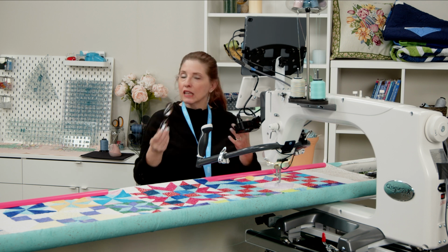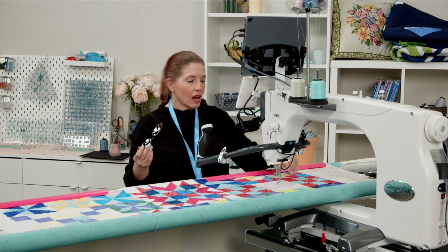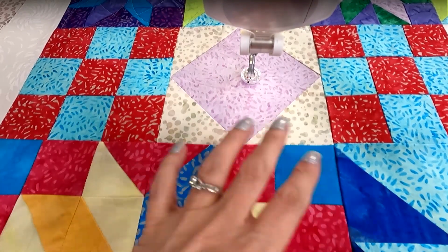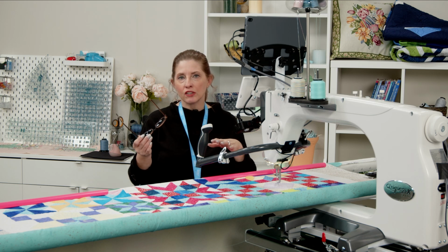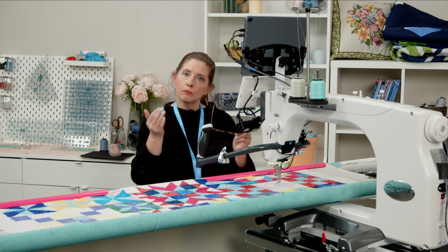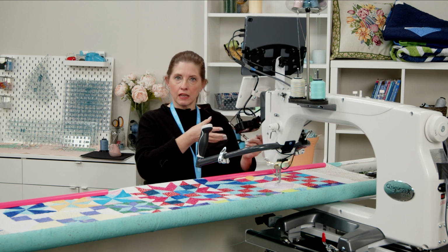One of the things that I like about the record feature is that I can take a ruler and measure a certain area, kind of do some pretend ruler work, and then take that into PatternCAD, because now I have whatever this shape is, and then I can draw something in PatternCAD that I want to fit into that shape.